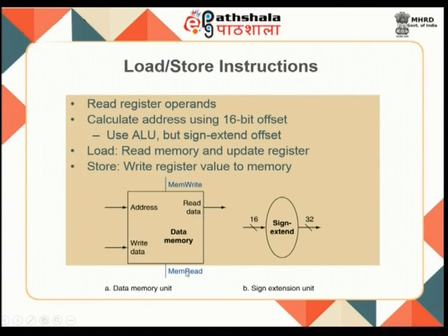And when you have to perform a memory read operation, you give a memory read control signal, and if it's a store instruction, you will have to perform a memory write operation. So, you will have to give a control signal called memory write. To the memory unit, you will have to give the address as the effective address. If it's a write, you will have to give the data that is to be written, and if it's a load instruction, the data that is read is produced outside the memory unit. So, this is what happens for a load store instruction.